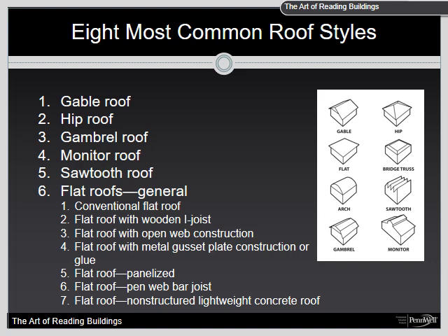Hazards. The hazards of hip roofs are similar to those of gable roofs. The presence of 2x3-inch or 2x4-inch trusses for rafters will produce results similar to those of lightweight trusses in gable roofs when exposed to fire. Although the spacing of the trusses may be reduced for truss, gable, and hip roofs covered with tile or other such heavy material, the collapse potential will be enhanced due to the increased dead load on the roof. Similar to the gable roof, reading the rafter tails can be an excellent indicator of the size and spacing of the rafters.